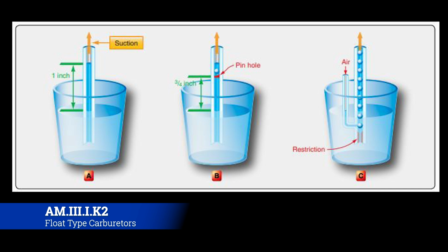And so this is primarily when you're just sitting at idle. Once you're running and gunning and you're at 2,500 RPMs and climbing, then this won't matter as much. But at idle, this is where the air bleed problems will particularly manifest.